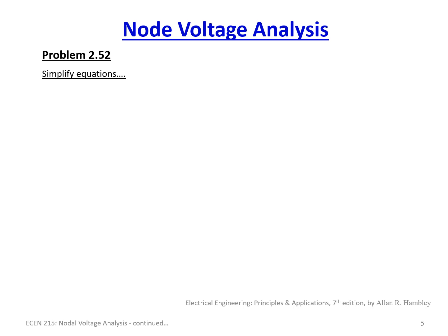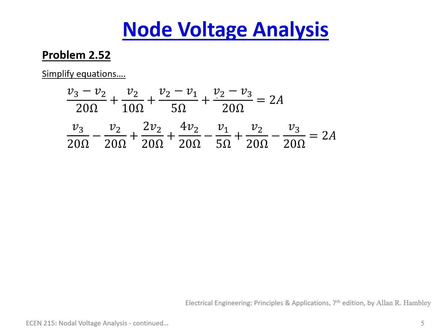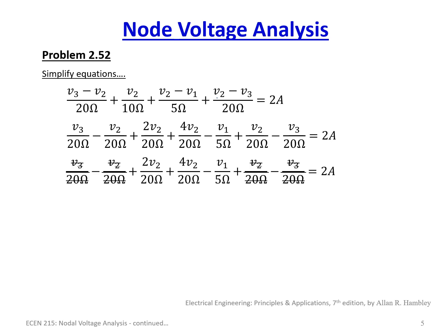So let's just start by simplifying our equations. We start with this, which is from our second equation. If we remember a moment ago where we combined the V2 minus V1 and the I15 volts, well, this is that equation. One thing you'll notice is the V2 minus V3 terms here will end up canceling out, but let's just go through and simplify. We expand things out, and then cross out everything that cancels, and we end up with this: 6 V2 over 20 ohms minus V1 over 5 ohms equals 2 amps.